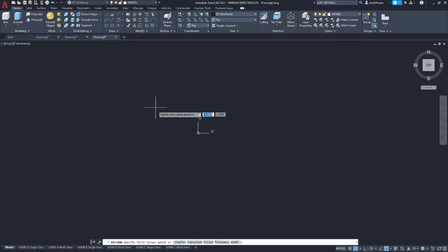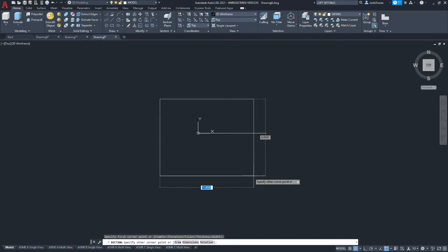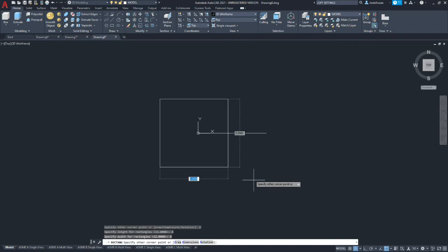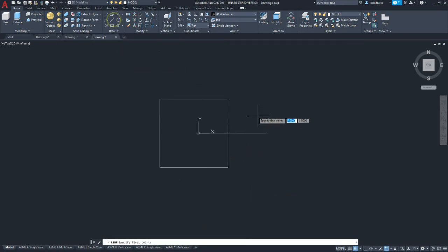So we're going to draw our first square. Actually, I'm going to go ahead and do my normal. I'm going to draw a line from origin over to the right with ortho on. It's just going to be something I can use to select on. We're going to draw a rectangle. With this rectangle, we're going to make it a dimension, so type D, 8 by 8. Okay, and then we're going to draw a line from corner to corner.